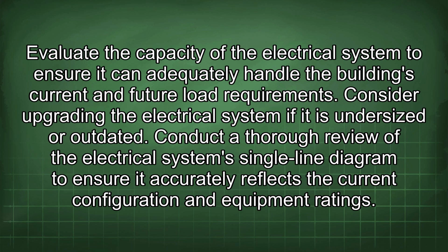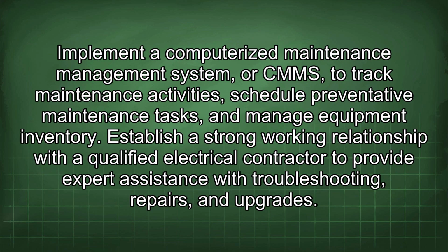Conduct a thorough review of the electrical system's single-line diagram to ensure it accurately reflects the current configuration and equipment ratings. Implement a computerized maintenance management system, or CMMS, to track maintenance activities, schedule preventative maintenance tasks, and manage equipment inventory. Establish a strong working relationship with a qualified electrical contractor to provide expert assistance with troubleshooting, repairs, and upgrades.